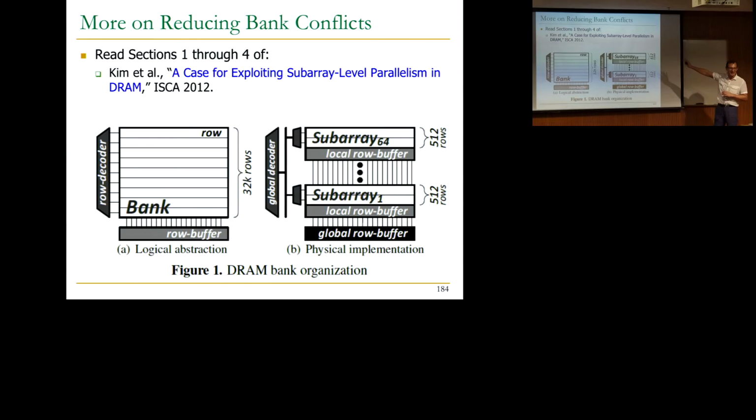I think this is a really good idea. But the DRAM interface is so hard to change, so it's not clear if this idea is going to be implemented. The Samsung and Intel paper that I mentioned earlier evaluates this idea. That was written in 2014. This was written in 2012. And they actually find benefits from that idea, showing that this is actually a good way of tolerating the long write latencies in DRAM. We almost had that as an industry standard. It was supposed to be DDR4E, but ended up with only one DRAM manufacturer wanting to do that.